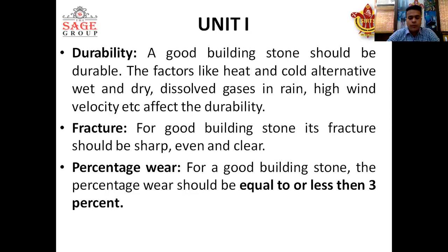Let me tell you about the fracture. A good building stone should have a fracture that is sharp, even, and clear. That means when a stone is broken into pieces, it has sharp edges, pointed corners, and a rough texture. The fracture should be clear and plain. It doesn't have round corners or round edges. It has clear and sharp points, edges, and corners.